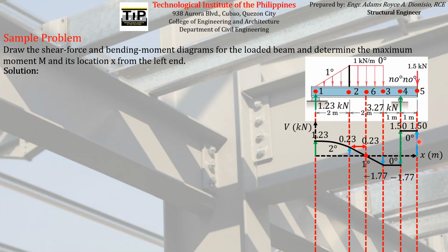So those are some of the things that we can see on a shear force diagram. Another thing is, obviously, we already indicated the location of the zero shear force. The importance of the location of the zero shear force is that the maximum bending moment acting on the whole beam is always located where the shear force is equal to zero.